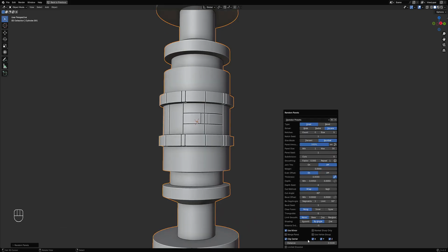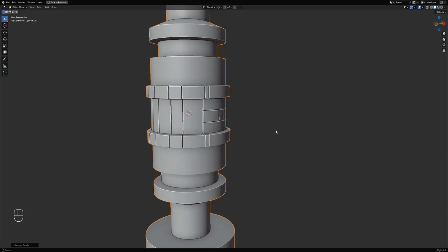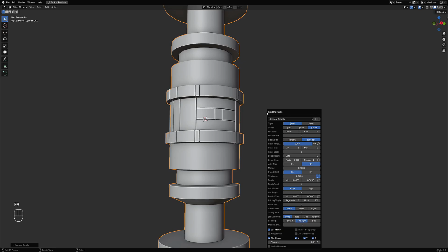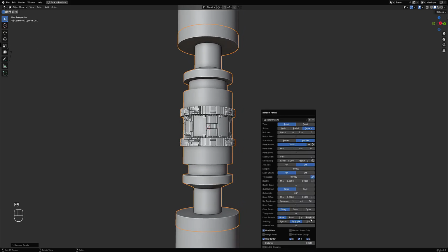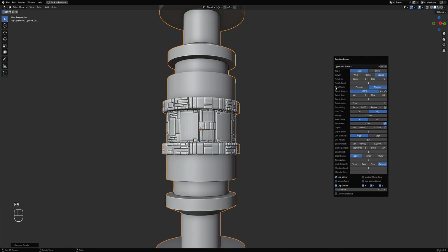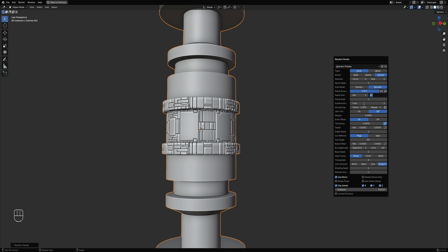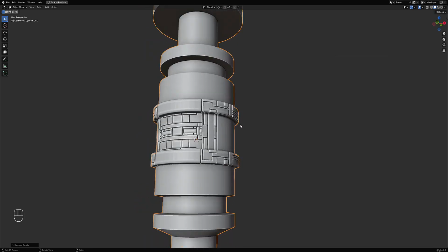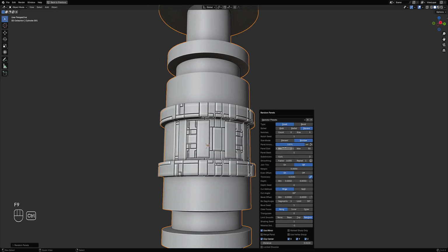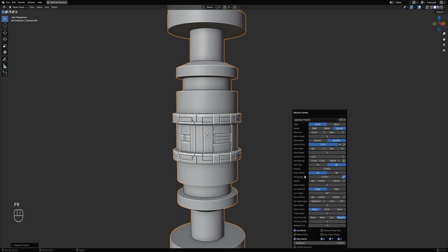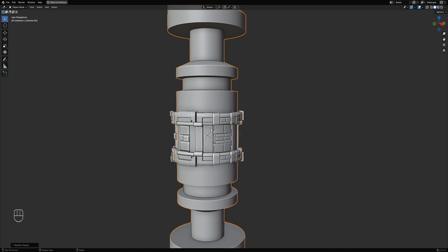Turn on even offset and change the clipping distance to clip the panel cut in the symmetry line. Toggle on random so we can randomize the shading and get a different look on our model. Make the panel islands bigger. Minimum is something like 5. And change the maximum depth value to create different or varying depth values for the panel islands. 0.01. Let's make it larger, 0.025.